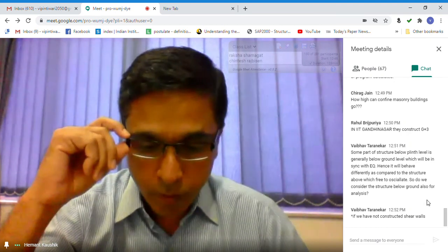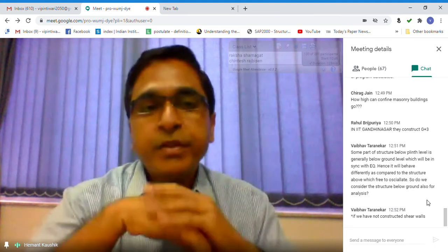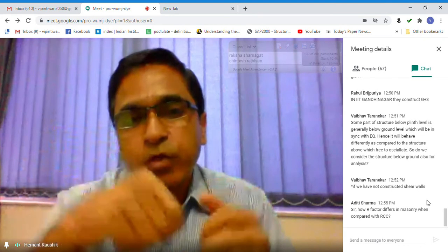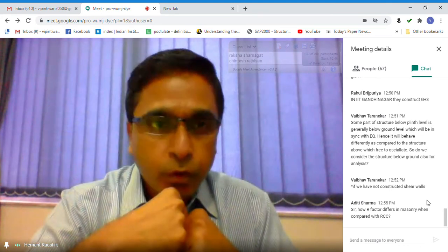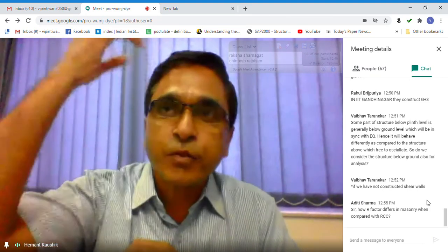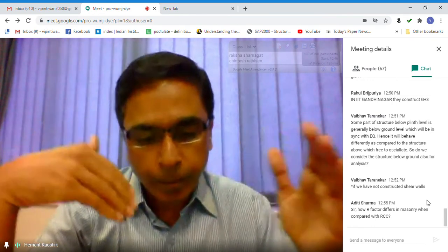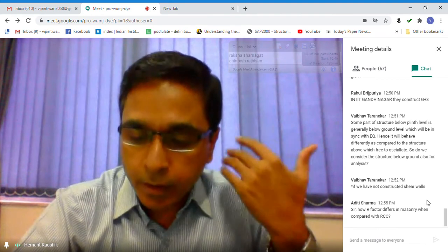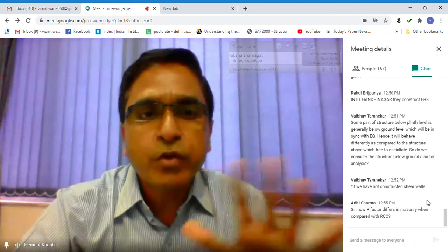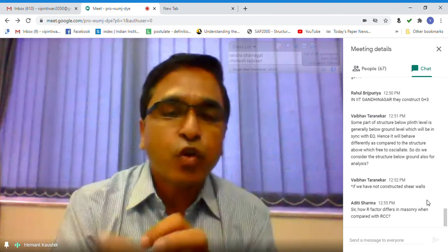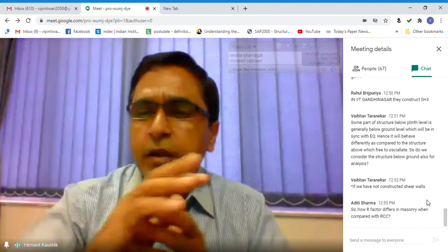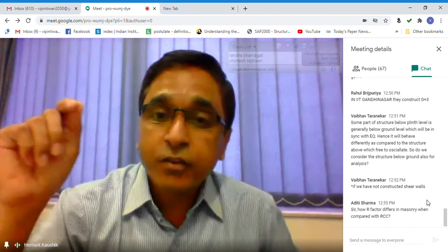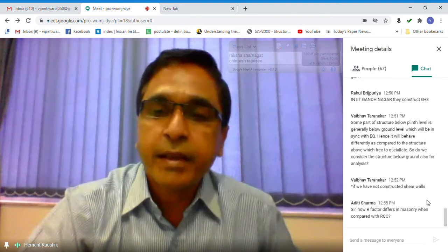Okay, now you tell me, how deep is the focus? It is about 10 kilometers, 5 kilometers, in some cases 1 kilometer, that is the depth of the focus. In some cases it is even 70 kilometers. Now these earthquake waves travel this much distance before they reach the structure. Now compare this 15-20 kilometers with a few meters of soil which is interacting with the structure. Do you really think that will change anything? That is not going to change anything. And during the first vibration itself, there will be some gap between the soil and the structure, which again refills, and then again it vibrates. So it is not proper to assume that we don't consider the soil below. We have to consider the entire structure. Like I said, if you think that a member contributes to mass and stiffness, you have to consider it in the analysis. There is no way you can leave it out.